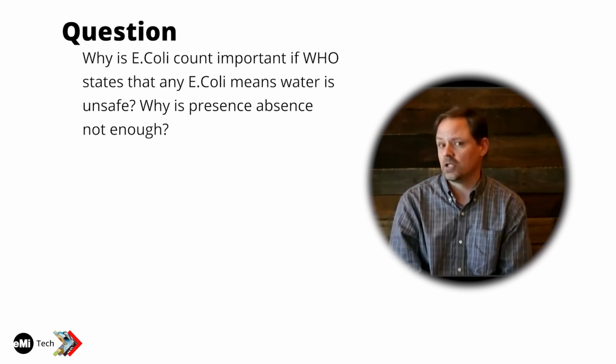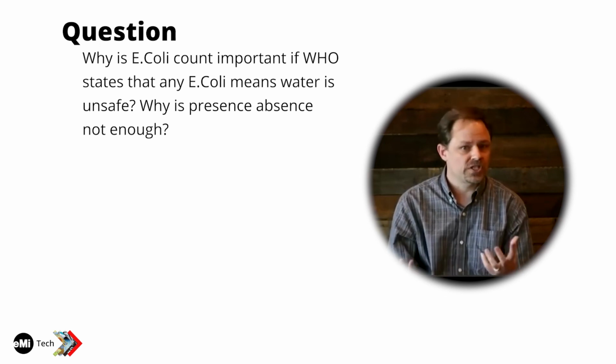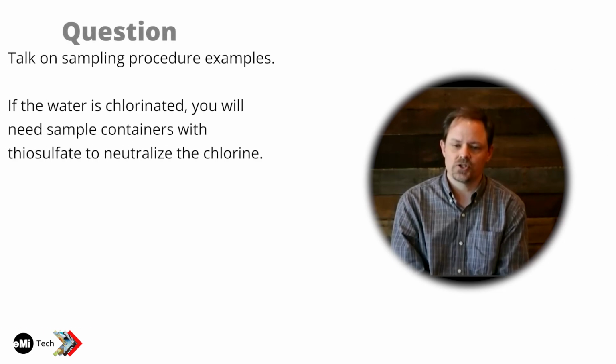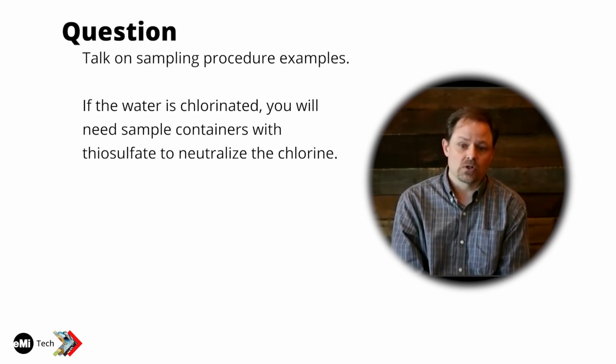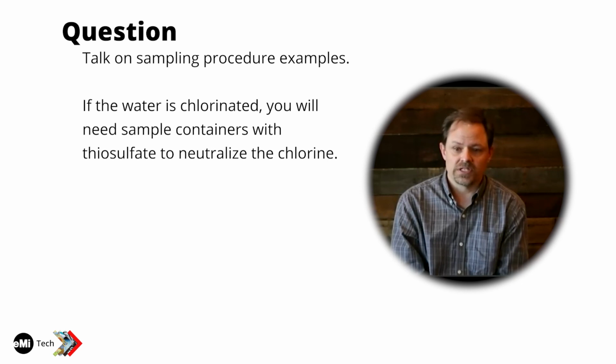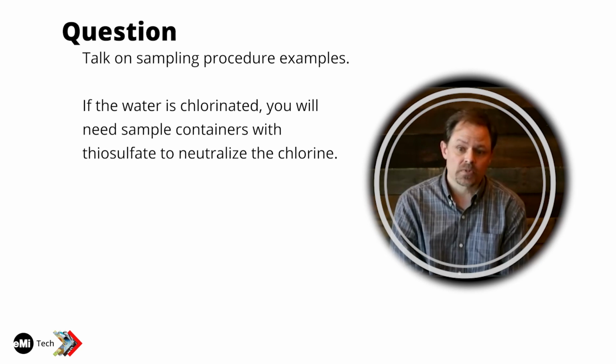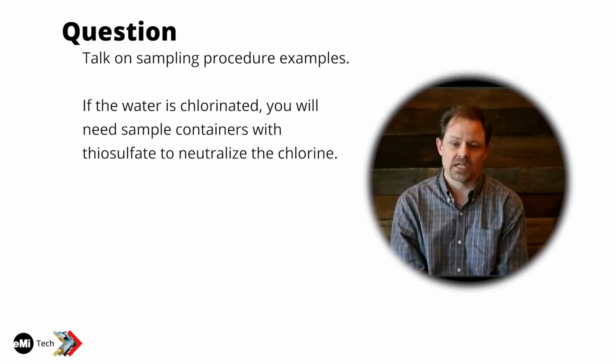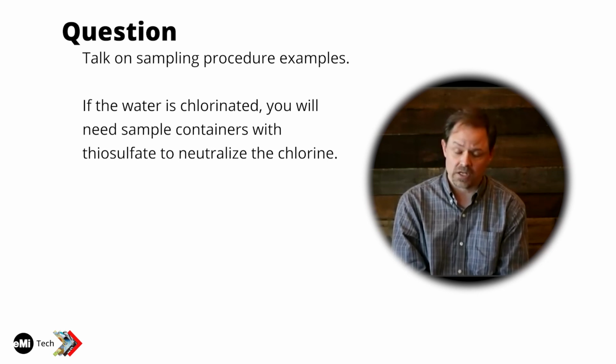Is chlorination alone enough, or do we want to chain a couple of treatment methods together? Maybe talk on the sampling procedure example. If the water is chlorinated, you will need sample containers with thiosulfate to neutralize the chlorine. Yes, good points. Whoever wrote that, that's an excellent point about the thiosulfate, and I'll add to that.